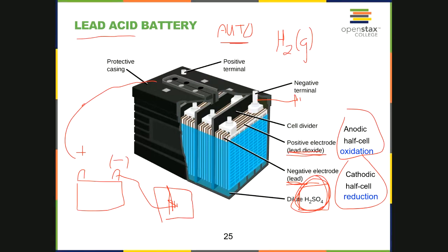So the first thing you're doing is connecting the two positives together, then you're connecting the negative from the battery you're charging from to a metal location on your car, away from the battery. So if there's a spark or something, it's not going to ignite the hydrogen gas. This is seriously a very dangerous thing to be doing, and you want to really be careful.